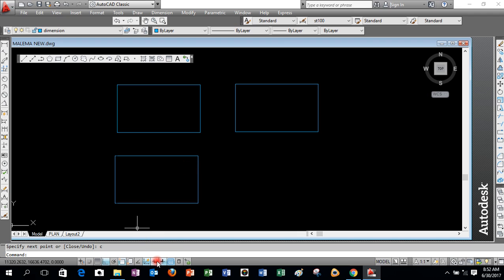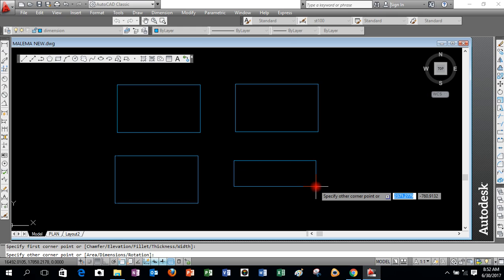But sometimes you can do this if you are to use the dynamic input. For dynamic input, you need to put this. It should be on. As it is, there is off, and there is on. Okay, so it's on for dynamic input, and so you go to the rectangle. You have a rectangle, and then you do that. As you can see, we have specify the first corner is that one, and then you are going to type on the blue, which is 2400.